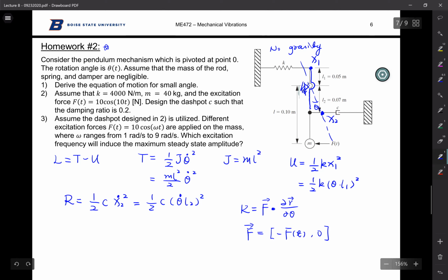And then let's find out what the R vector is. As I said before, you have to find where the force is applied, where the origin is. You connect this. You have to shift this mass a little bit, otherwise your theta will be 0, so your relationship won't be clear. So your R vector is sine theta L, minus cosine theta L. So your partial R partial theta becomes another vector, cosine theta L, sine theta L.